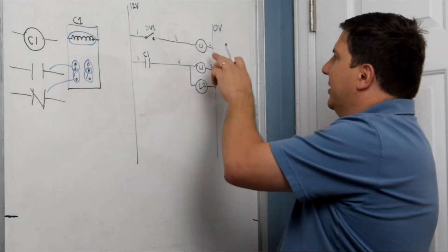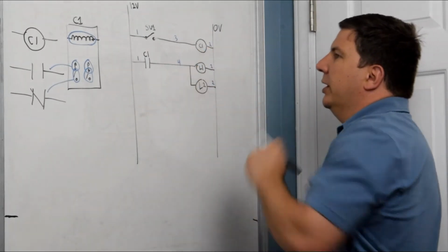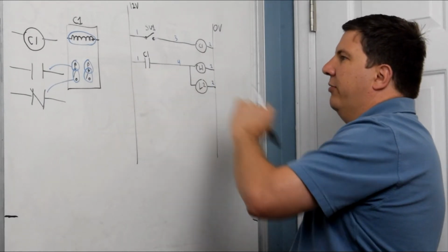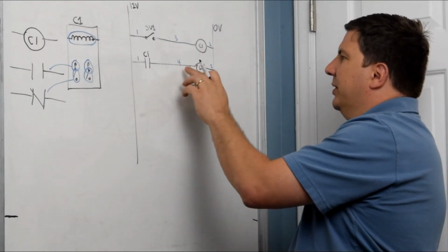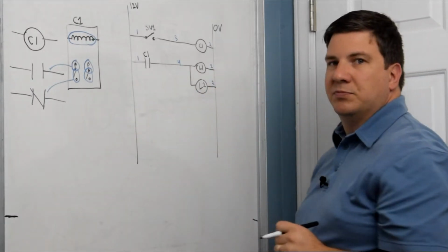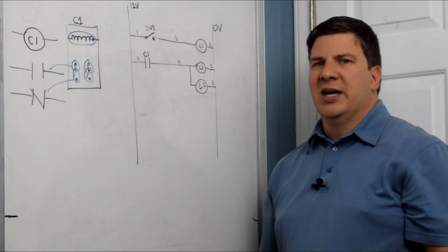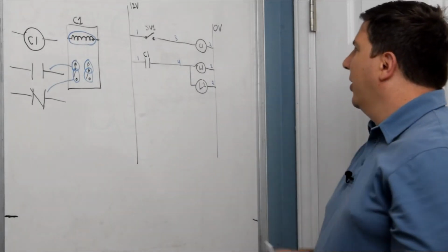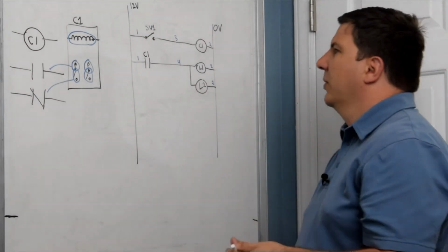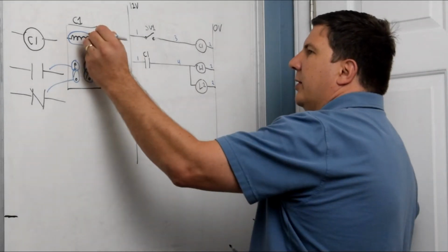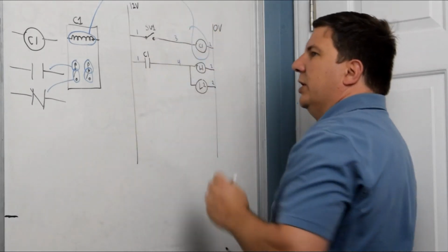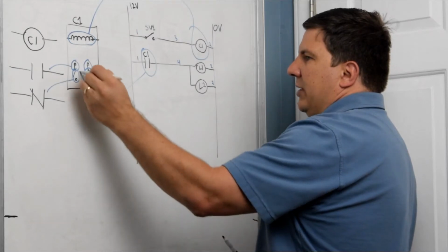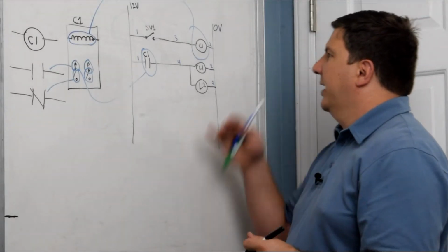All right, do I have a switch 1 that's got a 1 and a 3 on it? Cool. Do I have a control relay 1 that's got a 3 and a 2 on it? Excellent. Do I have a contact here that's got a 1 and a 4? And 2 lamps that have got 4 and 2. Excellent. I can check that very quickly as compared to the other one where it's just messier. It's not very good. Okay, so the other thing is, you can see here that we've put this over here. We've separated that part. We've separated this part. So that's now over here. So you can see that I can continue to add things.